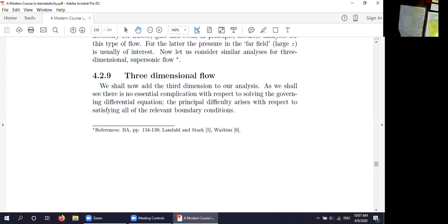because once the disturbance reaches the trailing edge and moves past the trailing edge further back in the flow, it cannot change what's happening on the airfoil. So that time is the chord divided by the difference between the free stream velocity and the speed of sound. And then if you normalize time, you can express that in terms of Mach number.